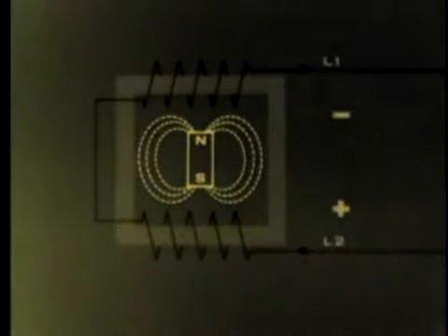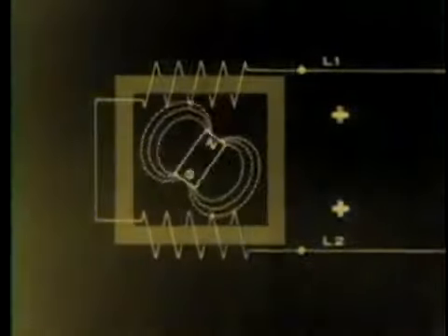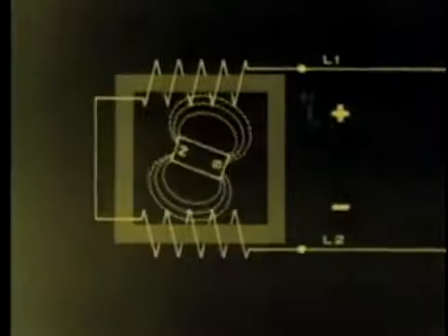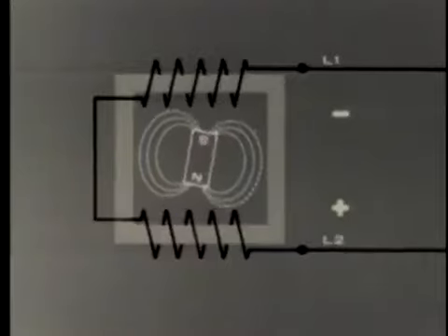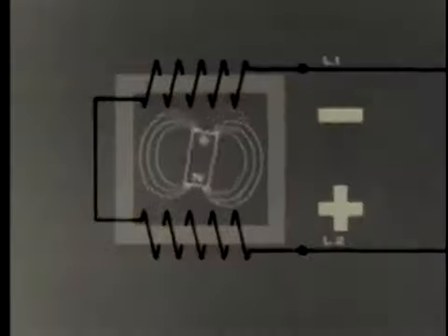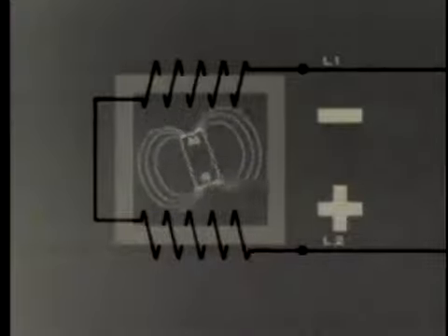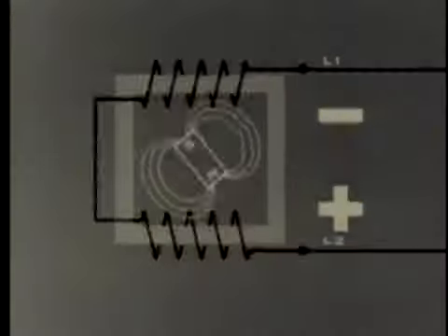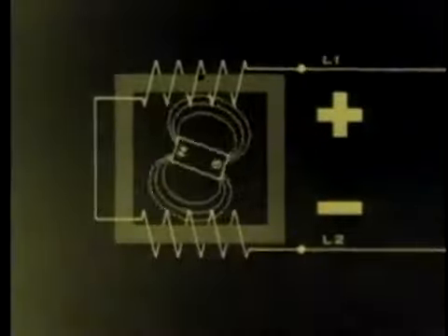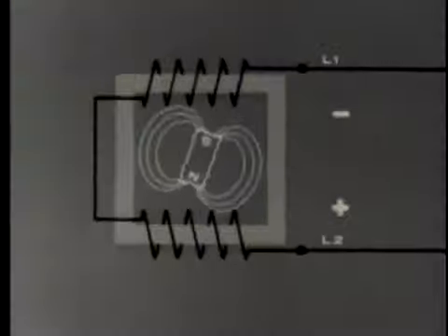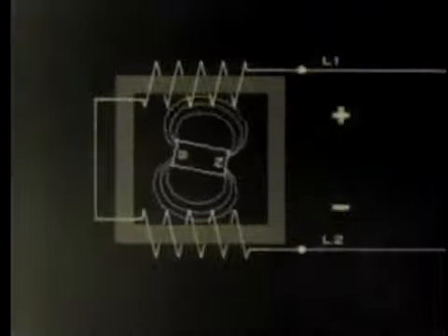Some generator magnets are located within a coil. Each time the magnetic lines of force of the magnet rotate across the wires in the coil, a potential is induced. Because of the difference in polarity of the magnetic poles, the induced voltage is alternately negative and positive. When we connect this generator to our line, it will create a signaling current, alternating at approximately 20 cycles per second.